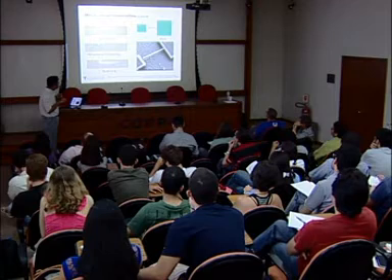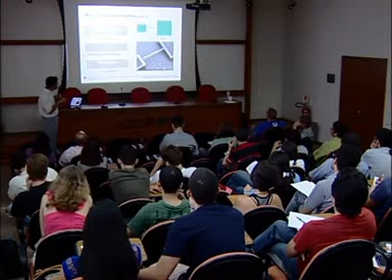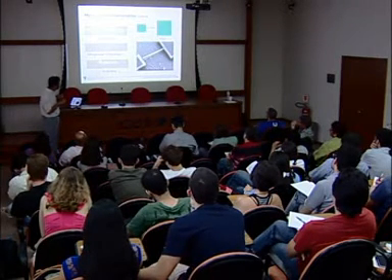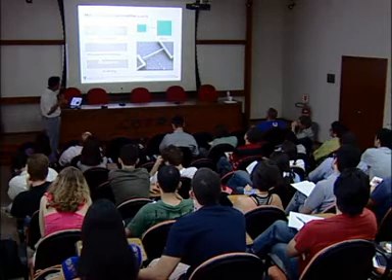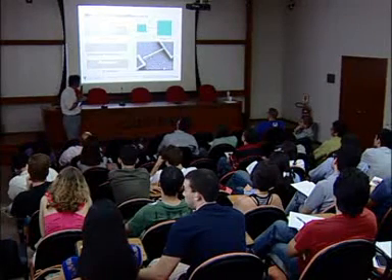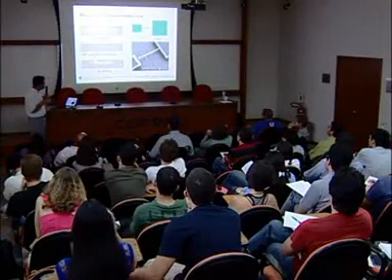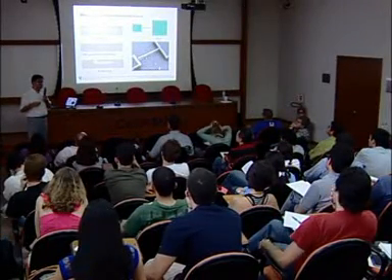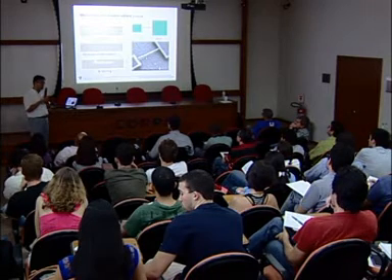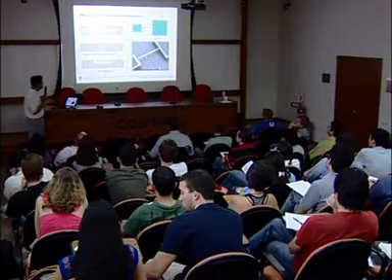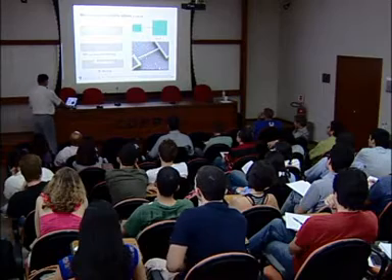Anyway, this dark structure is a silicon structure, and the white structure there's undercut. So this structure can be completely suspended in air, and when you apply electric potential to the bottom silicon layer and the top aluminum layer, it can be actuated by the electric potential. You have to apply a lot of voltage when you really operate this structure. About 100 volt or 200 volt should be applied to make the structure actuation.